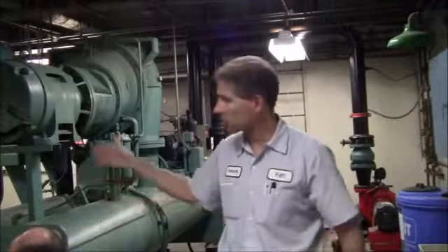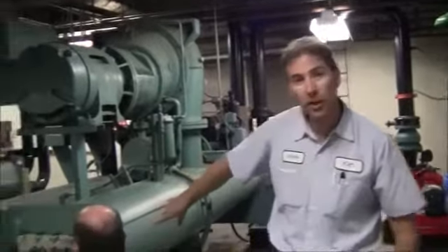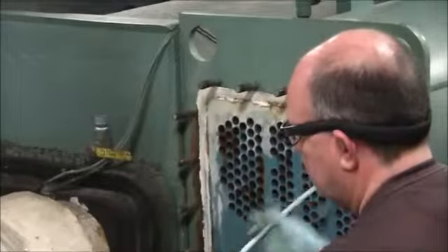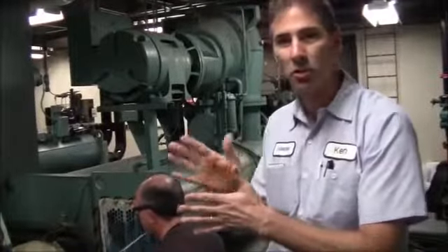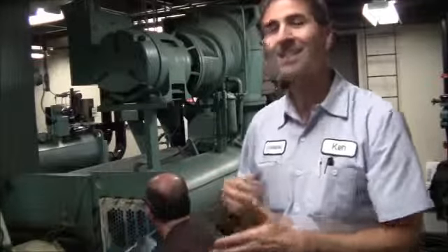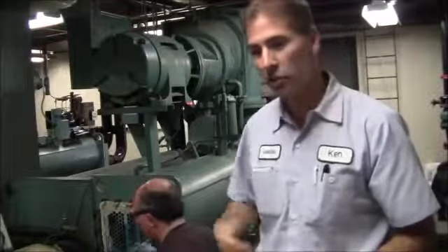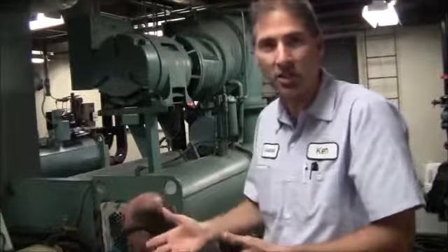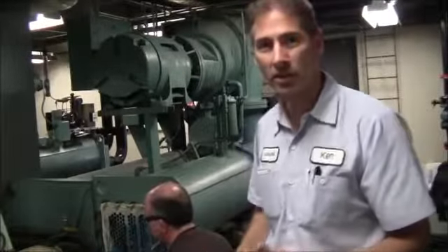Not on this chiller, but on the chiller next to it, we have a tube sheet repair, where you see that blue coating on this condensing tube sheet. Well, we've got some pitting going on in the chiller next to it, so we have to have an epoxy coating put on there, which is going to bring that back out to a natural thickness, extending the life of that tube sheet, therefore extending the life of that chiller. So these are some things that we're doing, part of the repairs and maintenance, to extend out the life expectancy of the chillers.